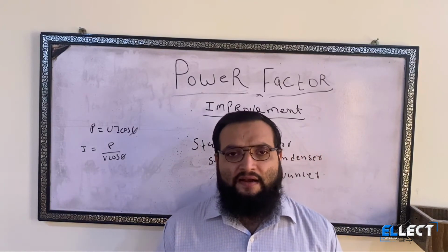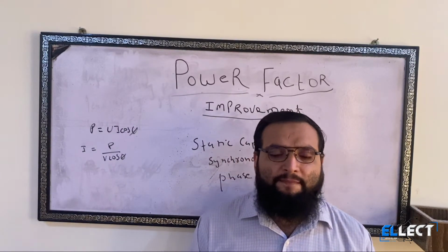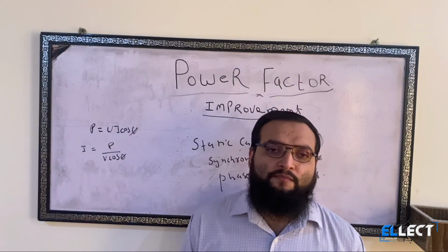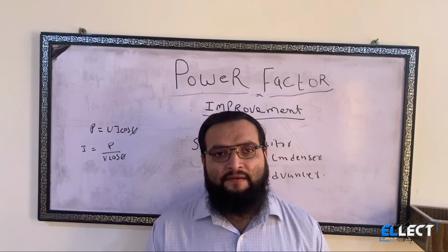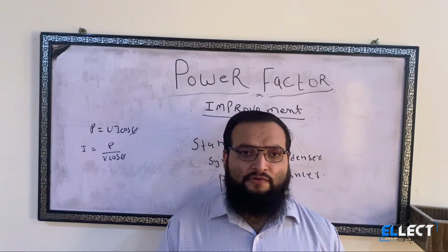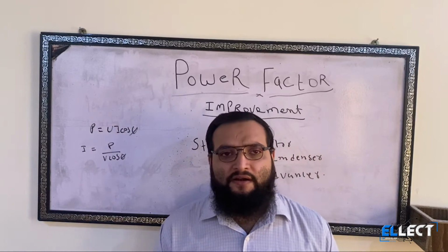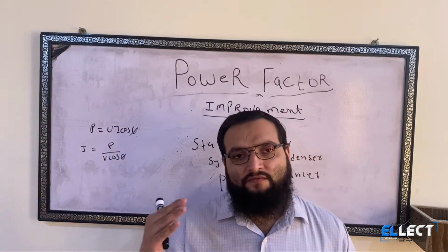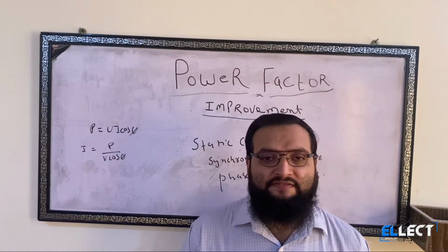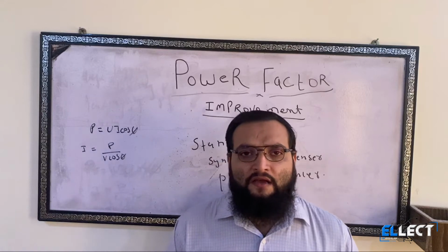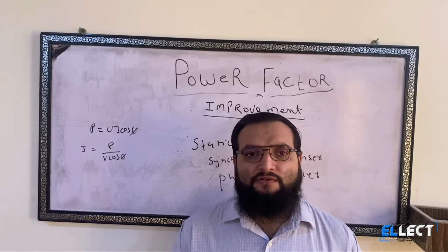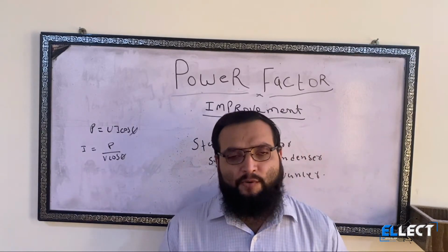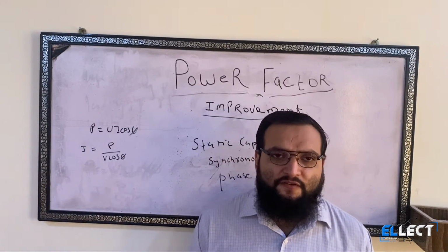But we can say that static capacitors may be installed at large places, say in parallel with induction motors and power transformers of high rating, so that they neutralize the lagging component of current drawn by the induction motor or transformer, and the power factor of the induction motor as well as the transformer is increased. It is very beneficial for electrical bills and many other ways. Stability of the system will be improved and device efficiency will be higher.